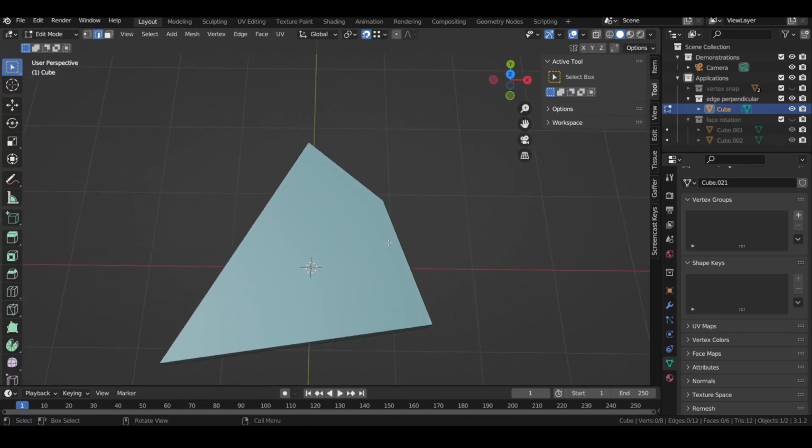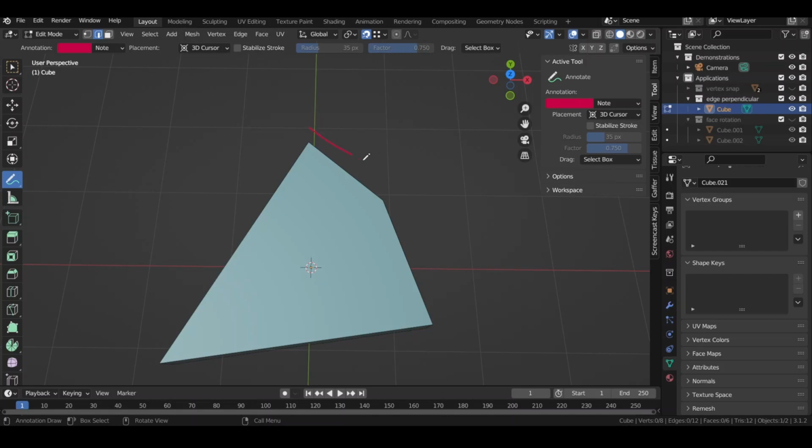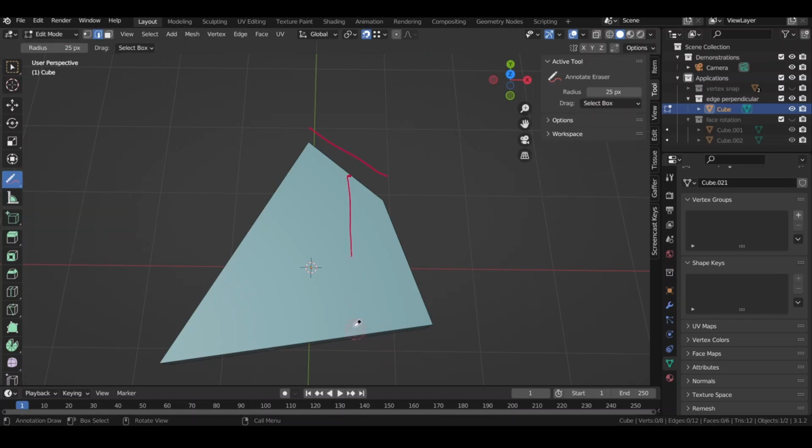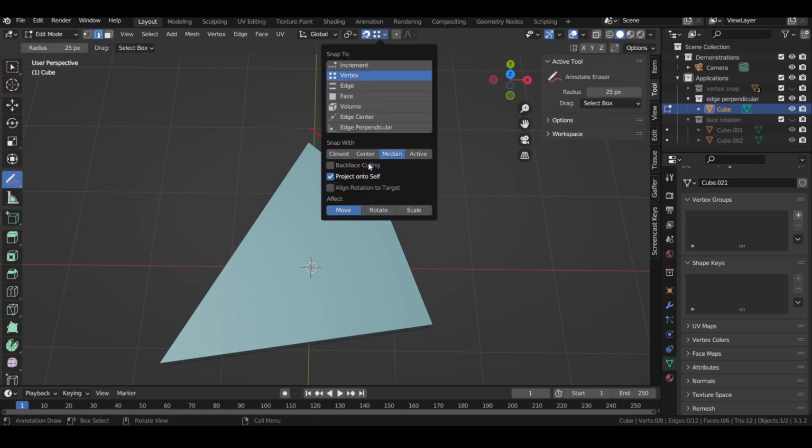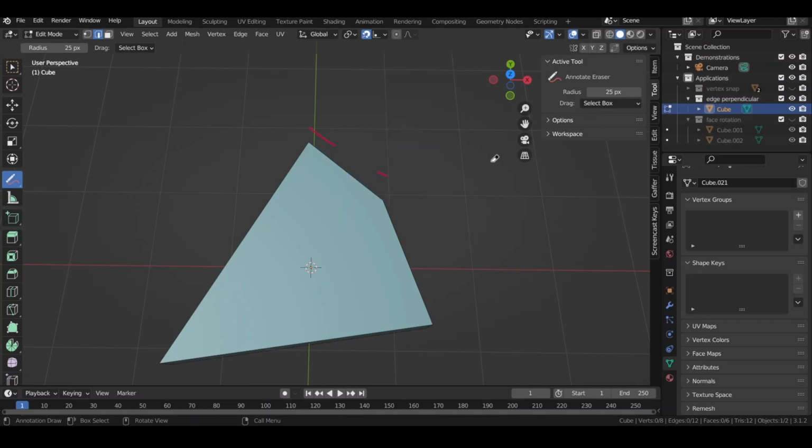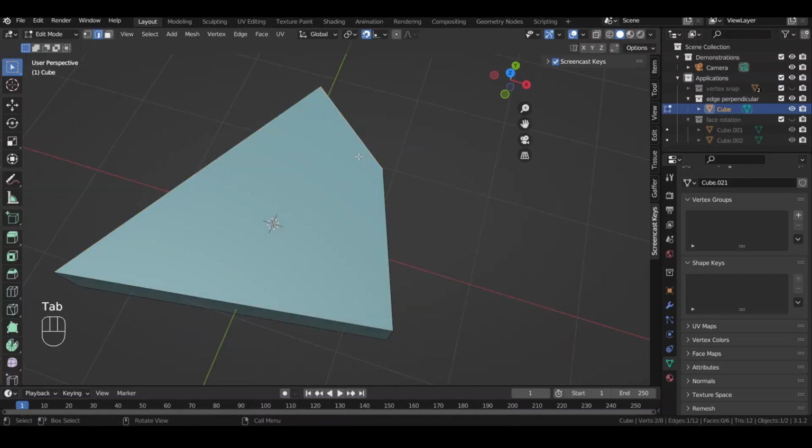And what you want to do is, from a point on this edge right here, so let me highlight it, from a point on this edge right here, you want to have a point, and from that point, draw a line to this second edge right here, such that the line is perpendicular to this second edge. So what we'll do is approach it by using our knowledge about snapping to edge perpendicular. All right, to start, you just want to pick out your first point.